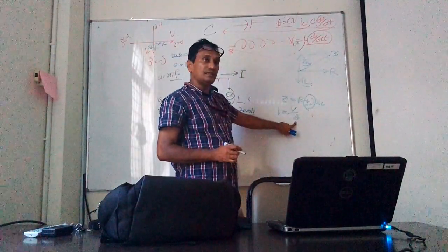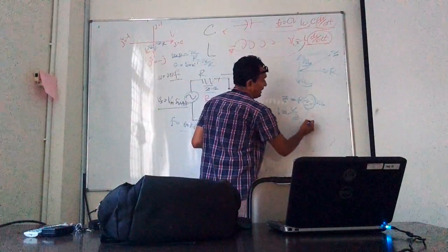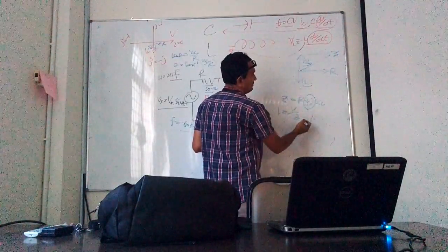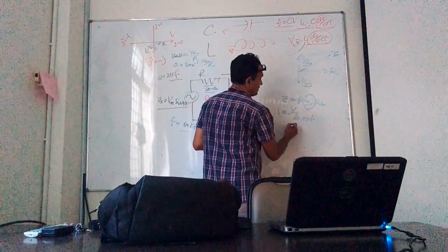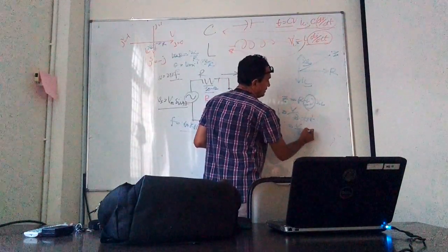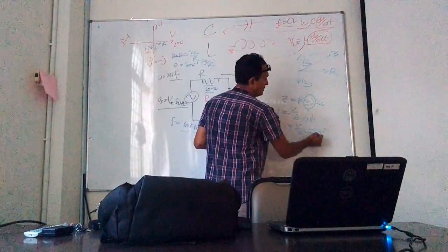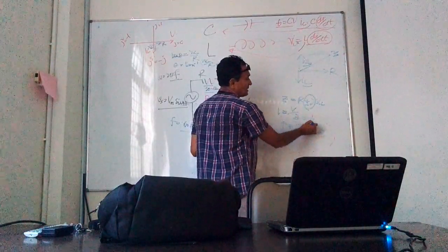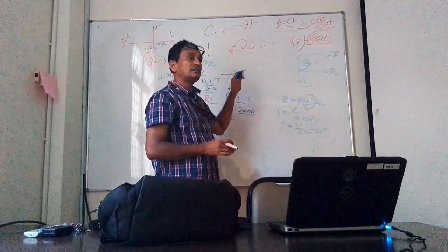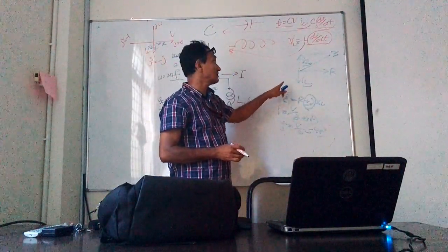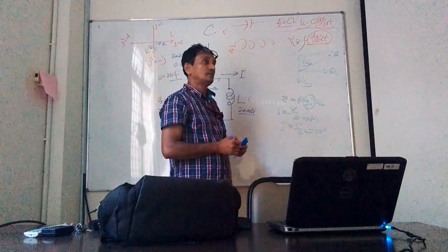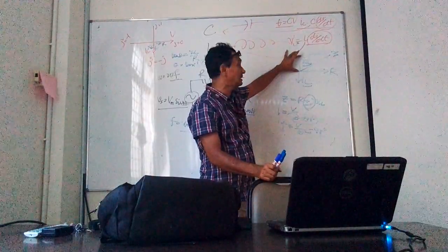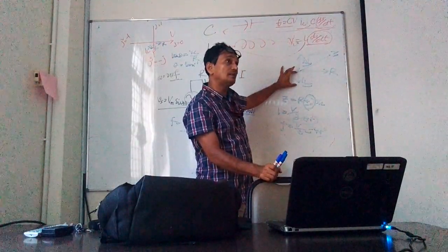Any angle of the impedance, if you say it is 45 degrees, so minus 45 degrees or plus 45, definitely Z is 45 plus, so V by Z should be minus 45 degrees. It means that current will be 45 degrees lagging whenever impedance itself is leading. So this is the relationship between leading and lagging function of this vector. Sorry, yeah, because this should be the impedance, inductive reactance should be leading, inductive current should be lagging.